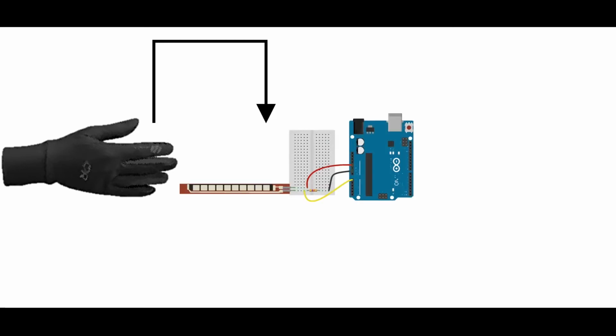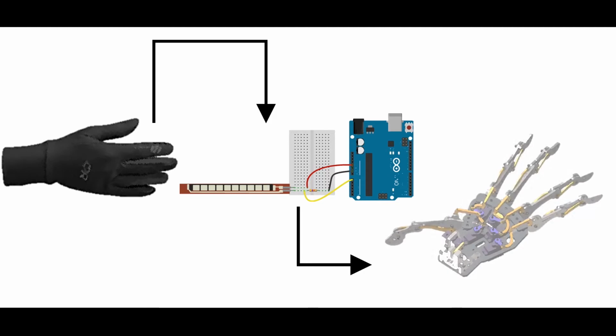Technical aspect: the user wears a control glove and can control the animatronic hand precisely. So, we are using some sensors for this process to happen. Those are called flex sensors. Depending upon the bending of the flex, the resistance will increase so that the servo motor will do the appropriate action. We will dive deep into these terms and topics in the later part of the video.